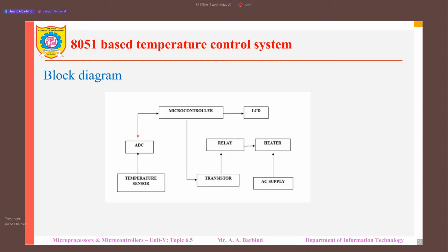Whereas if the input to the ADC is 5 volt, that is the full maximum, then the output of the ADC will be all ones, that is 11111111. That is the maximum output the ADC will have. Whereas if the input is midway, let us say 2.5, then half of FF is 7F, that is 127 or 128. So that will be 7F or 80H.